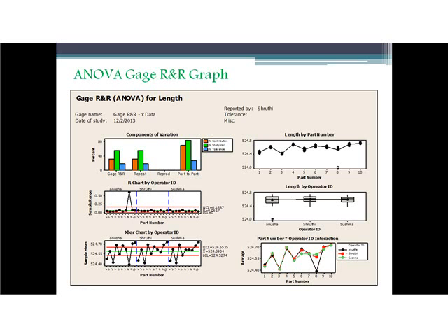And coming to the part number and operator ID interaction, here we can see the lines are virtually identical and operators are measuring the parts similarly. And coming to the length by operator, here the circle represents the means, and the asterisk represents the potential outliers, and the line is parallel to the axis. So the operators are measuring the parts similarly on average.